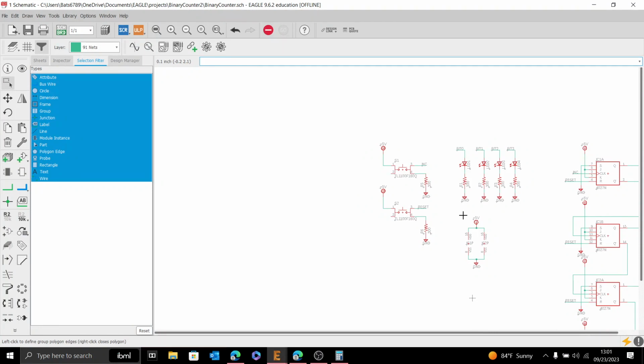When you push a little switch, it's really hard to see unless you get an ultra fast camera to capture it. I have seen it with one of those, I think it was several thousand frames per second. If you push the switch, you can actually see a little bounce with the metal contact. And if you hook up an oscilloscope to capture the voltage out, you can actually see a ripple. Sometimes that ripple is bad enough that you can actually get multiple inputs.